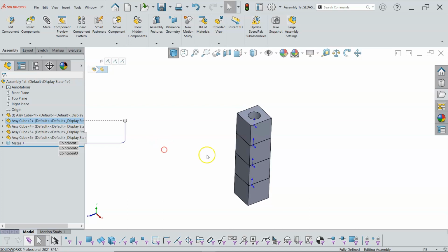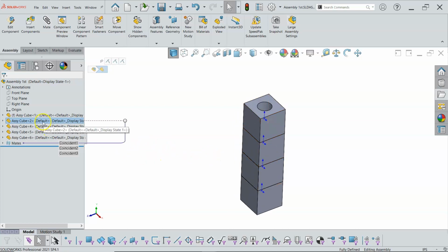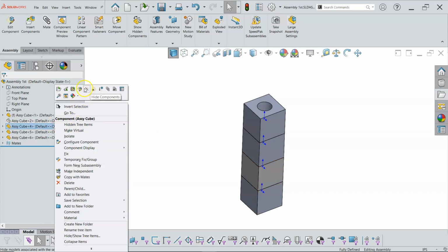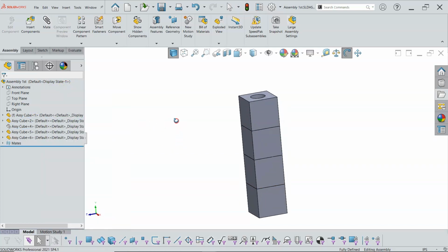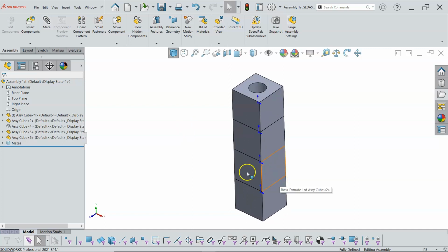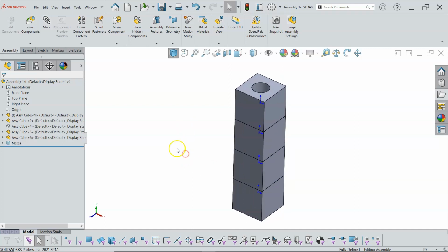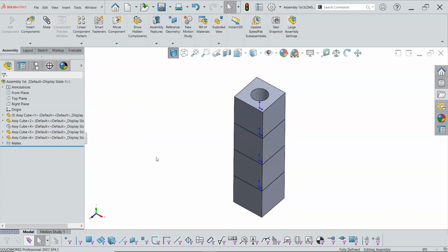So I show the components. I think I have the two objects occupying the same space thing going on again because of the hide. So let's hide, show. All right, so you can create situations where this is going to get kind of confusing, so you have to keep a running track of the instances that you've brought in and kind of what they're doing. If I were to bring in another instance, it's not going to go back and fill in number 3. It just keeps incrementing and goes to number 7, and then we'll continue on.